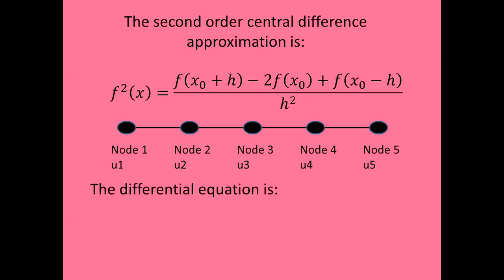Now the next step is the differential equation which is to be satisfied. Del square y by del x square is equal to M divided by EI, and we apply this second order differential equation to the ith node, where the value of i is going to vary from 2 to 3 and finally 4.